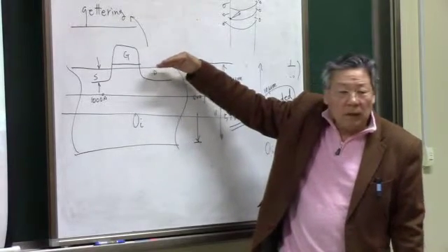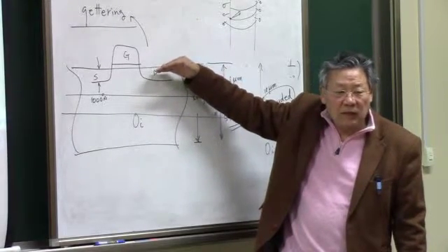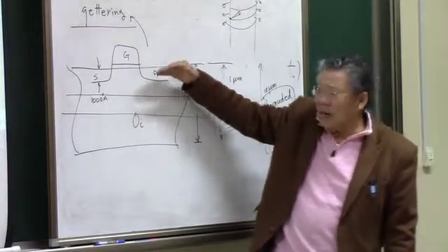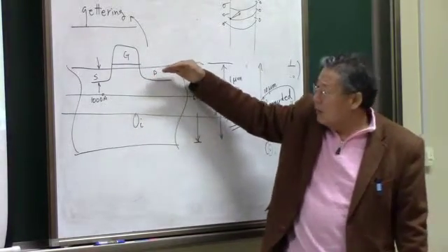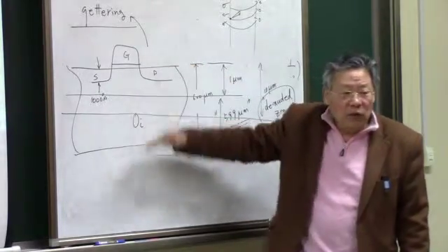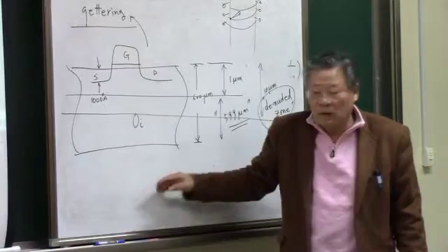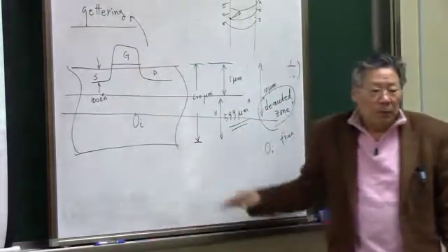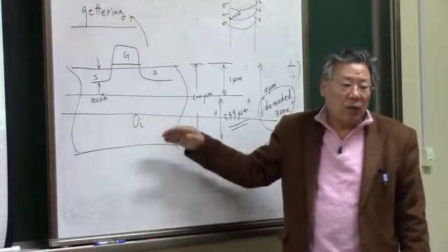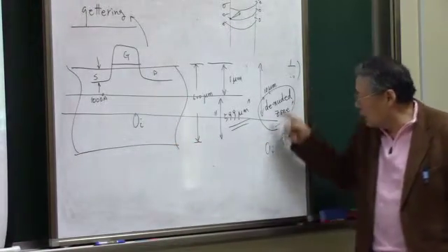Then the top oxygens or defects, any other contaminants like iron and things like that, those kinds of impurities will be diffused towards the high potential area, which is on the opposite side of the wafer, so that we can create the denuded zone.